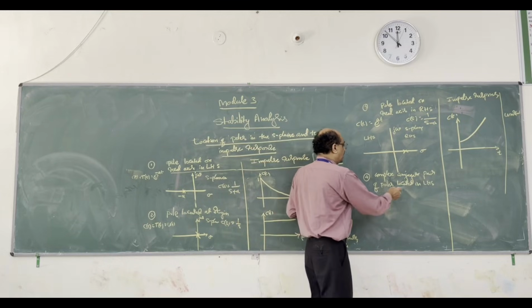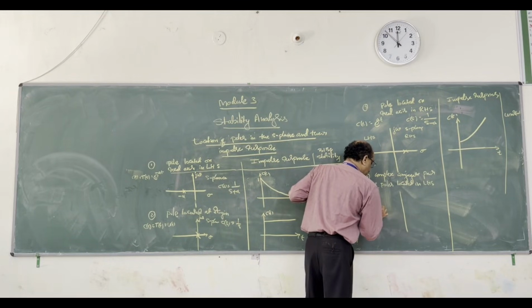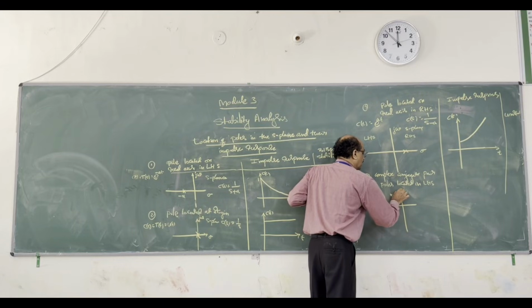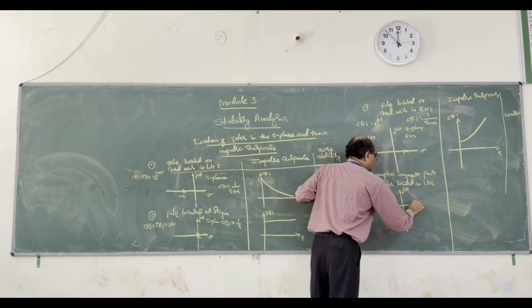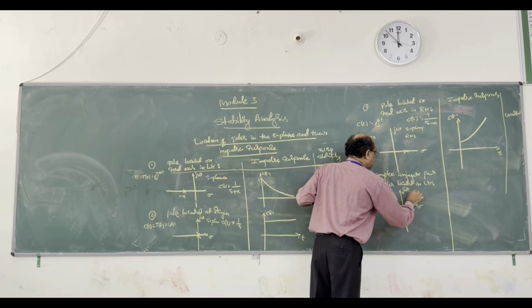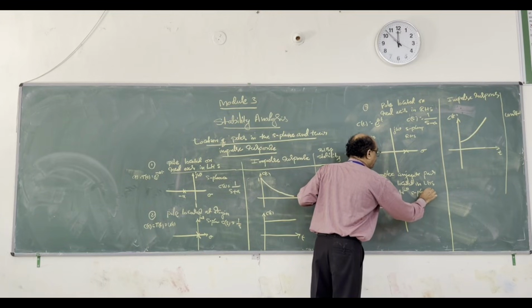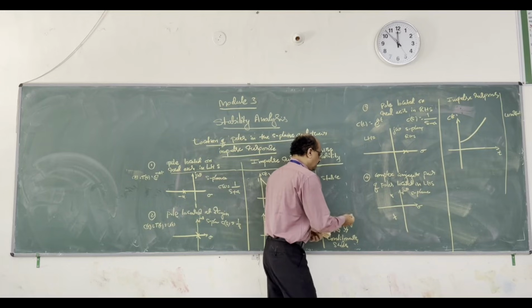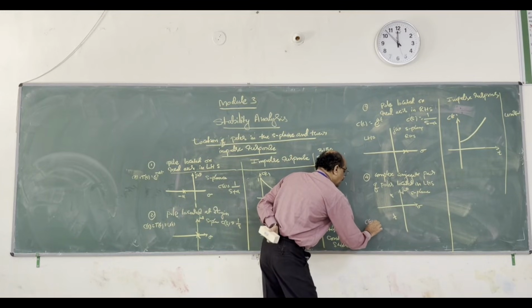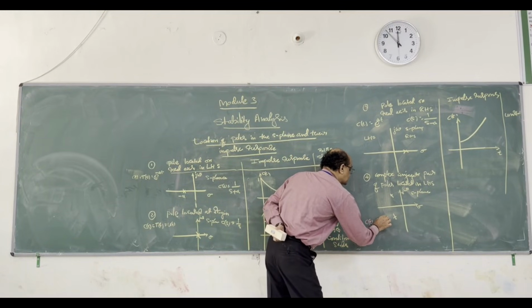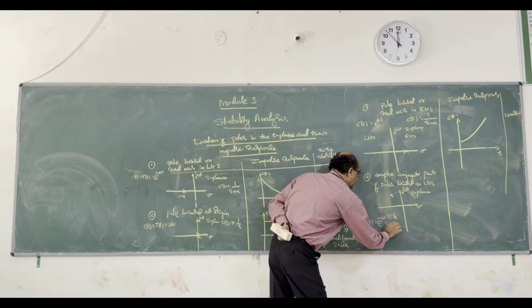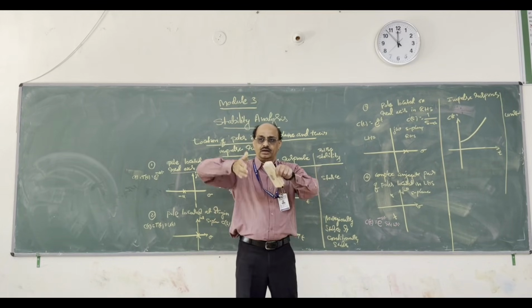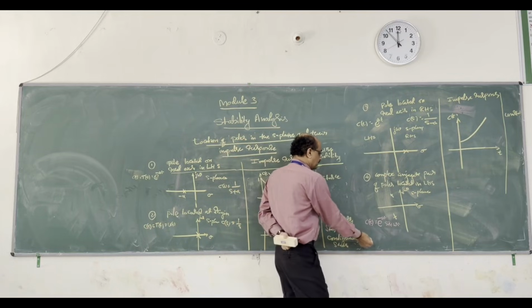Clearly stated. Let me now take any complex conjugate pair located somewhere here, in the s plane with j omega. The nature of c(t) is e power minus at sin omega t, an underdamped response.